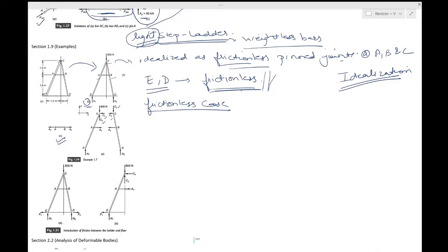Okay, so note that the unknown force Ax is again shown as is from the link, and N1, N2 as you go along. Now note that the unknown forces Ax, Cx and Cy are shown consistently according to Newton's third law. That is, the action of the leg C on the link AB is Ax, while the action of the link AB on the leg C is Ax.